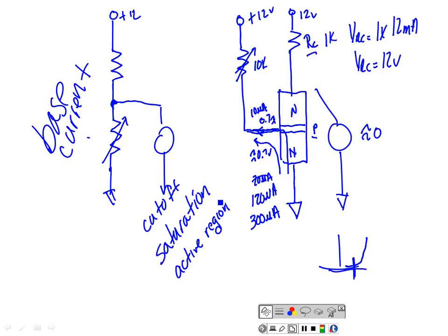And if you know that ratio, then if I can measure the base current, I can calculate the collector current as long as I'm in the active region, right? You understand? Or if I know the collector current, I can calculate what base current would cause it to run at that, because that ratio is a linear ratio. I mean, it's almost perfect.